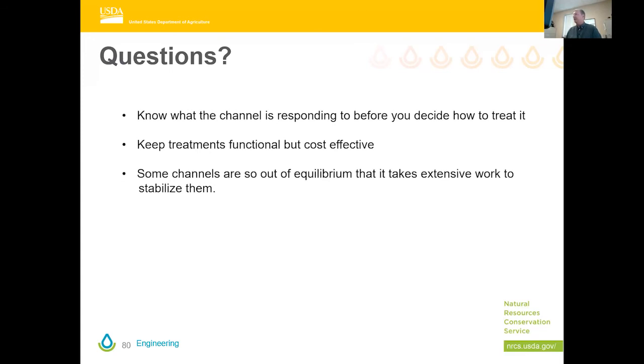Okay, to wrap it up, just know what the channel is responding to before you decide how to treat it. I think too many folks think that just trying to channelize or pile things in the stream is going to stabilize it long term. And occasionally they get lucky and it works. But in general, it's best to understand how a channel is responding so you can decide what treatment to use.